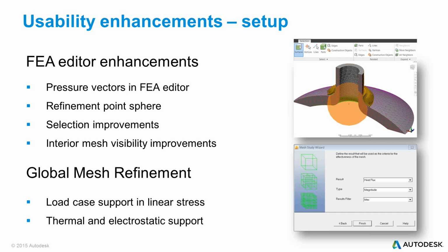The mesh refinement studies are an important part of any simulation, right? We don't just analyze our models with the default mesh and look at the results and take those results as our final results. We always recommend that we perform mesh refinement studies.